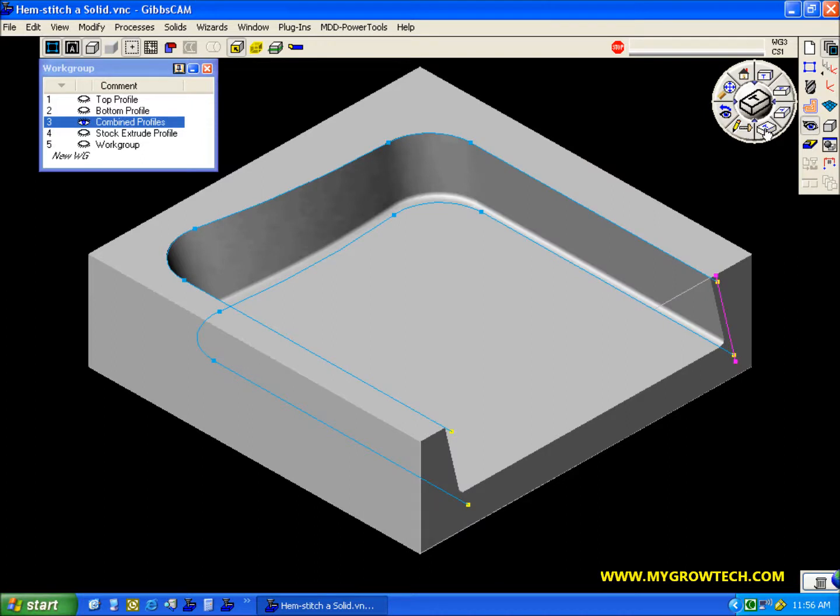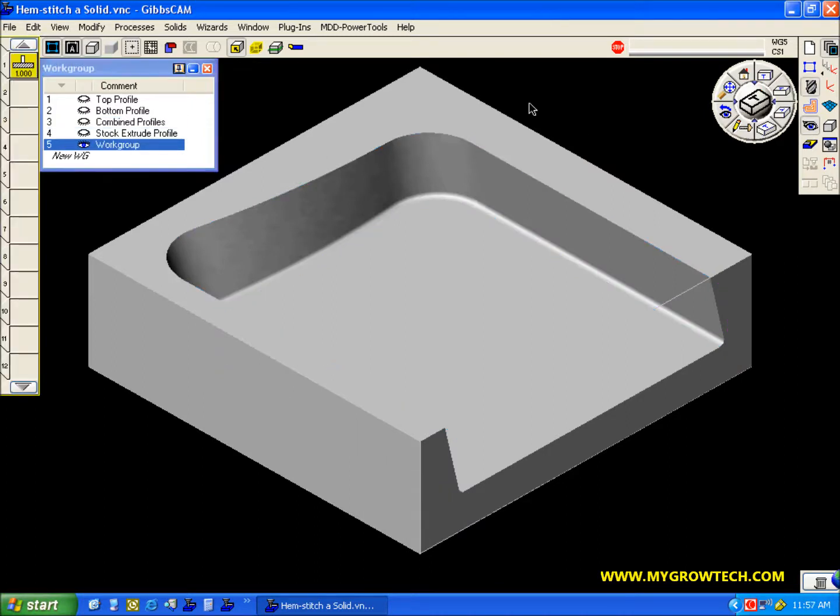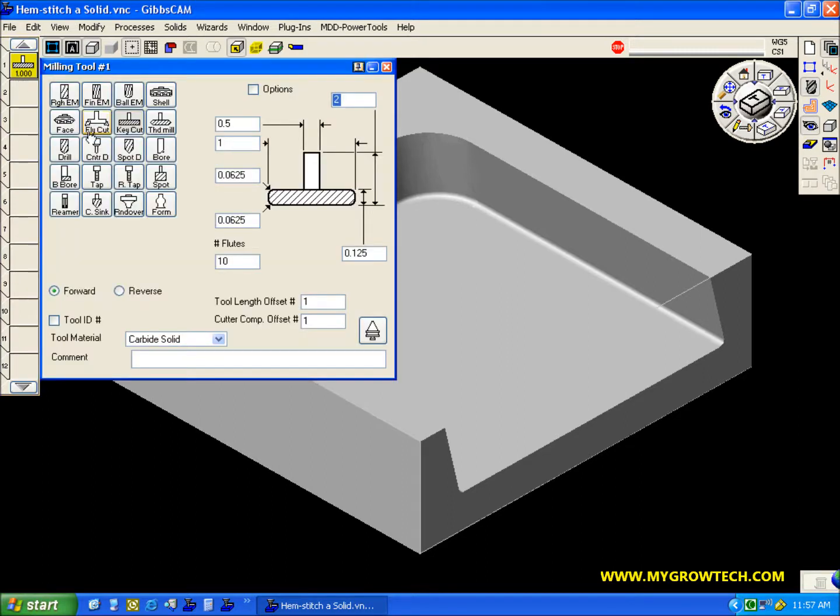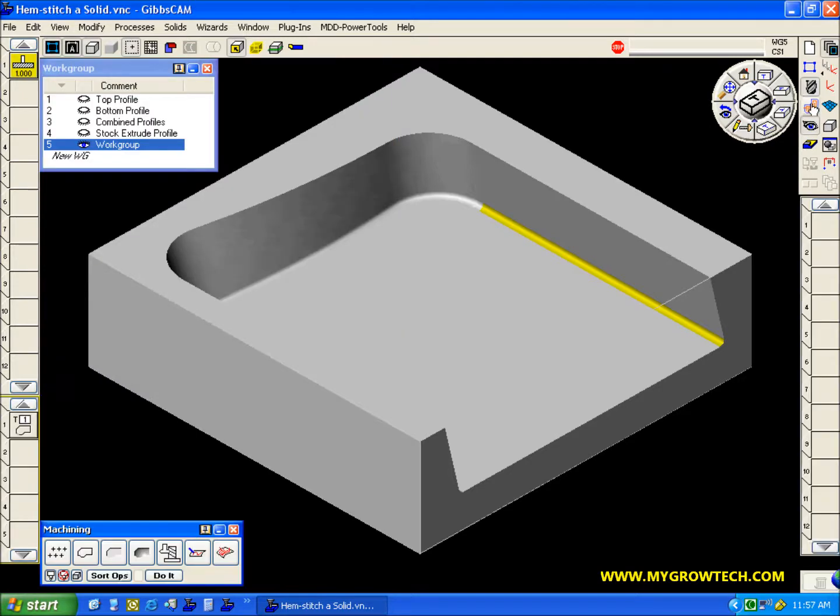As we have to go through and cut this, the best way to do this is to use a key cutter. So let's open up the key cutter, and we're using a 62 thousandths top and bottom radius with a double value, 125 thou. This radius here is equal to the floor radius right at this edge, and that's where I came up with the number.